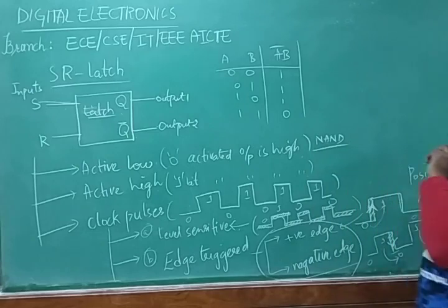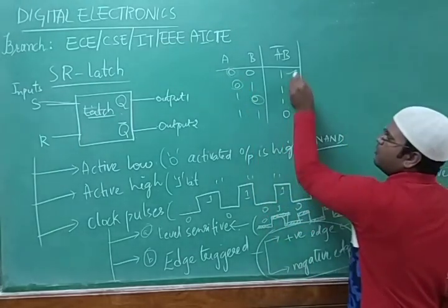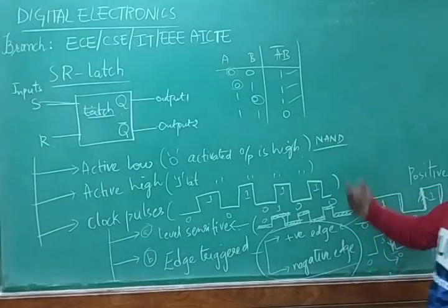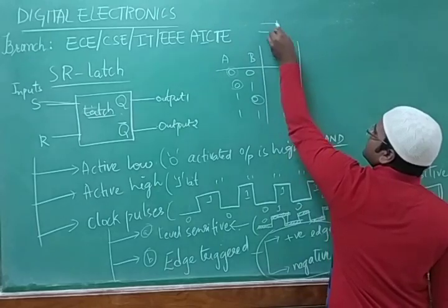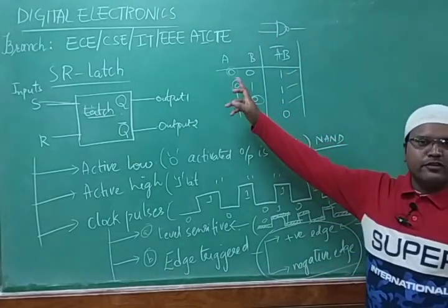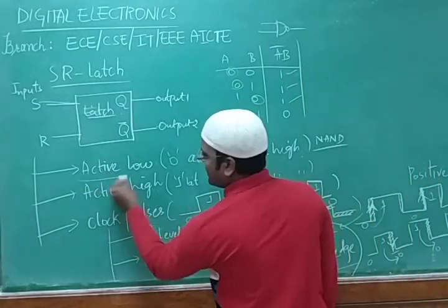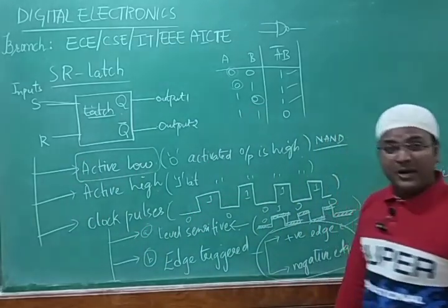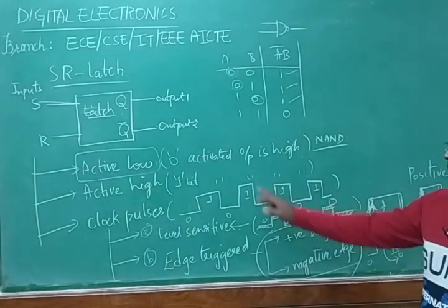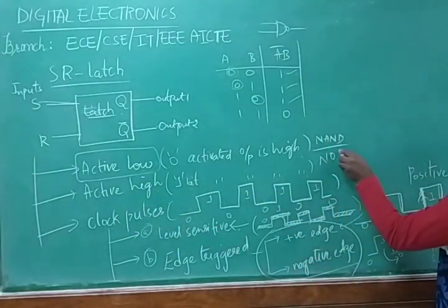And this is for 0. That means if you have a 0 bit, it is producing the output, right? That means it is active low. So the NAND gate symbol will be like this. When any one of the inputs is 0, the output is high. So this kind of designing is called active low pin designing or active low gate level designing. Clear?